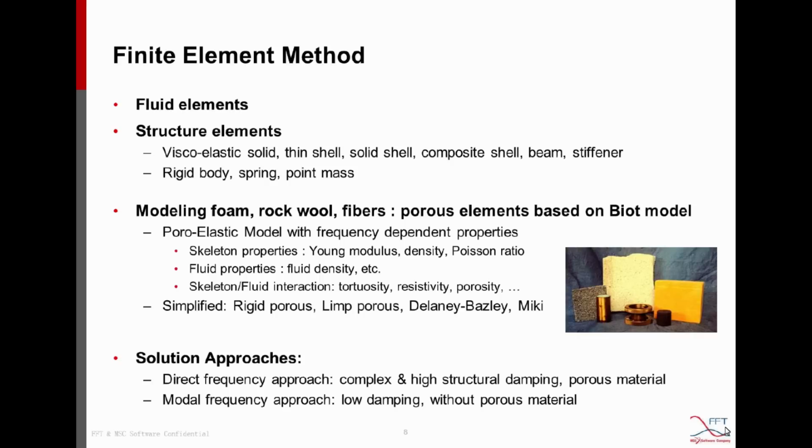Then, when the mesh is created, we need to create the physical component. So we will use fluid elements for the air gap. We will create a structure element. In this case, we will use the solid shell element and the beam element for the structure.